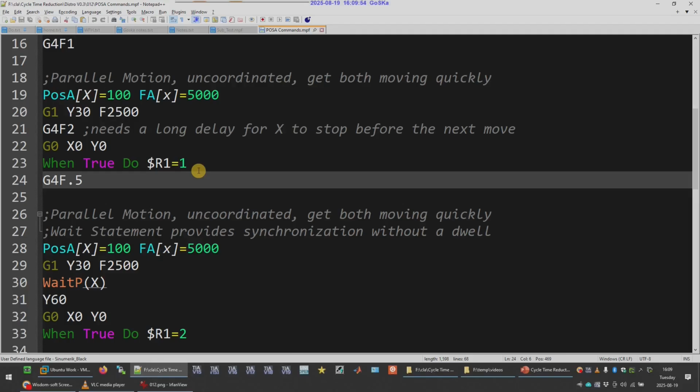Again, this is going to be for axes that have to move somewhat uncoupled, like you're trying to get a whole bunch of them ready for a tool change that are all moving out in free space. If you have fancy end effectors with many axes on the head and they just all have to retract at the same time to some known location, we'll worry about when they get there together later. That's the kind of function we're looking at.